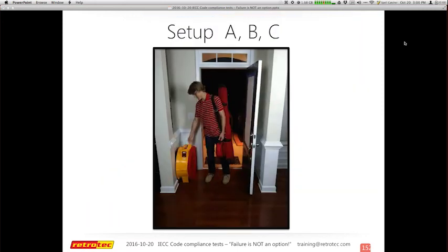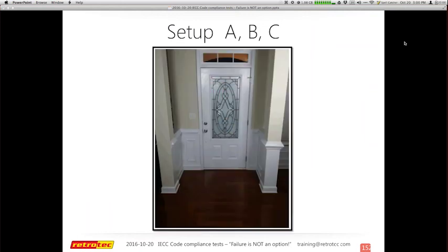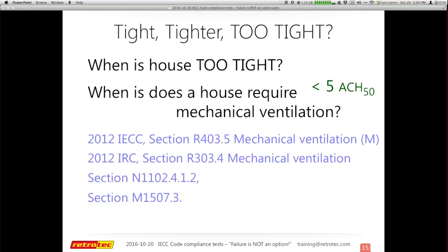When is it too tight for who out there requires a manual J? Oh, someone says, do you subtract joist area between floors? You do not. You actually are measuring from outside to outside. There are requirements about where is a room in terms of its ceiling height, whether it's counted. So I'll go through all of that in the webinar we'll have in November. And maybe we'll just do something like that directly.